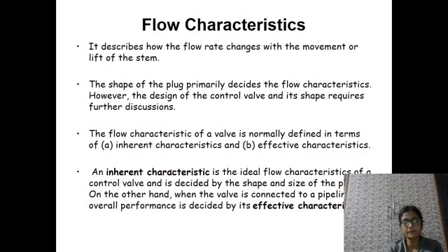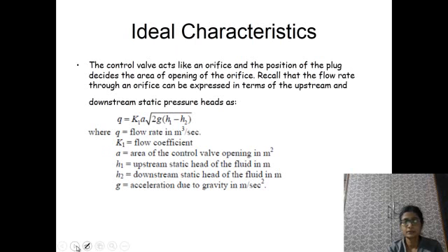And effective characteristics is the actual characteristics of the valve, which depends on the performance of the valve along with the path, that means where it is fitted in the pipeline, and the overall performance depending on the type of fluid flow, because if the fluid is a thin fluid flow, or if the fluid is a thick fluid, then that will matter for the flow rate.